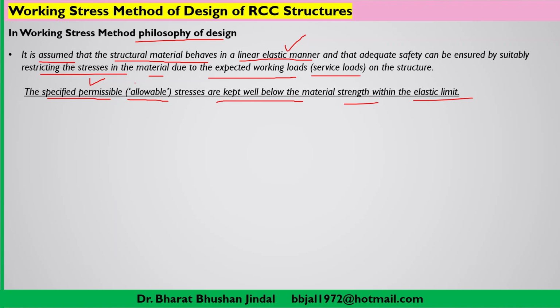As per this methodology, we reduce that strength for our calculation. We can take it as allowable only 10 MPa. So concrete of 20 MPa strength will be assumed as having 10 MPa strength.